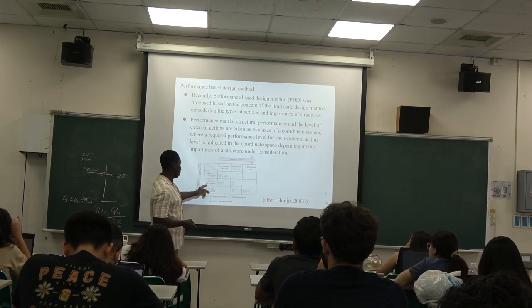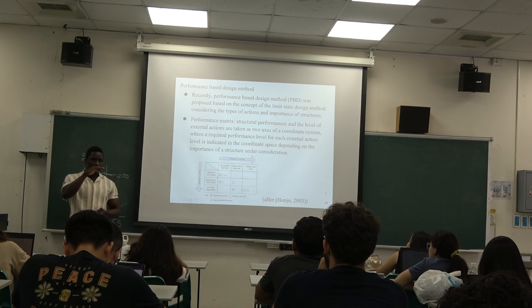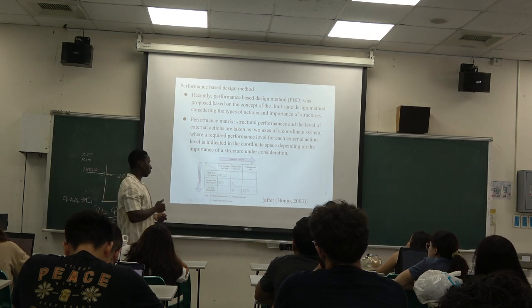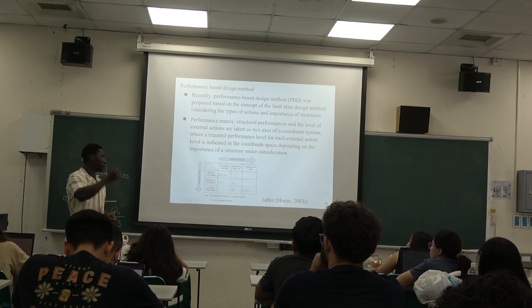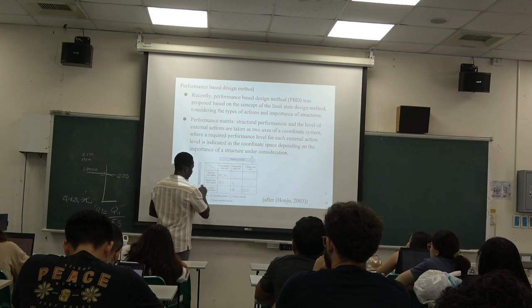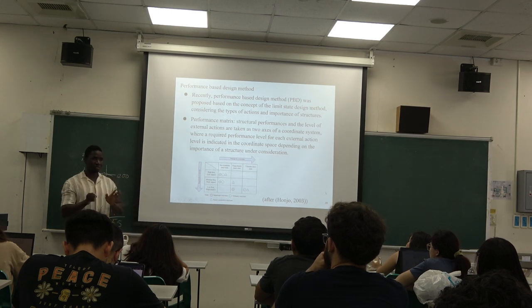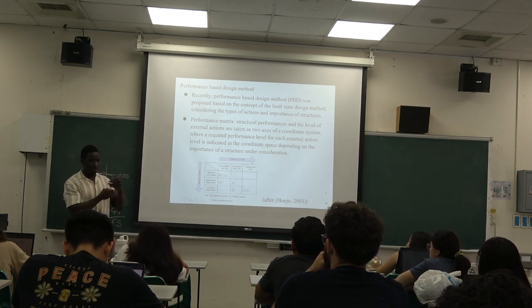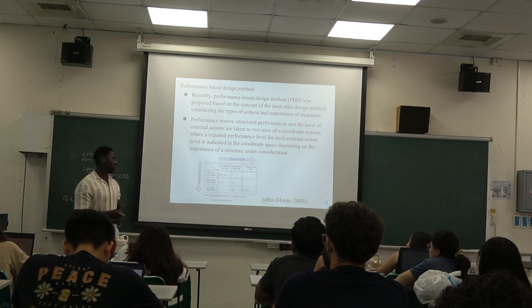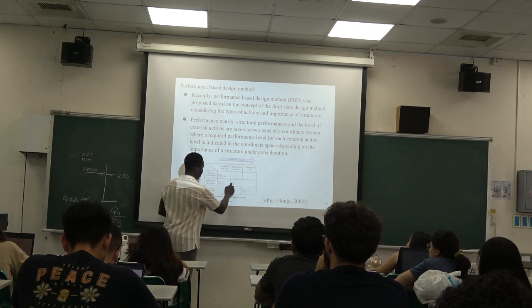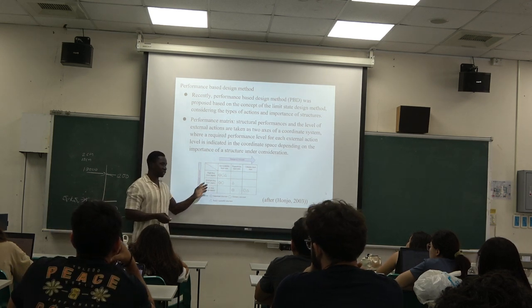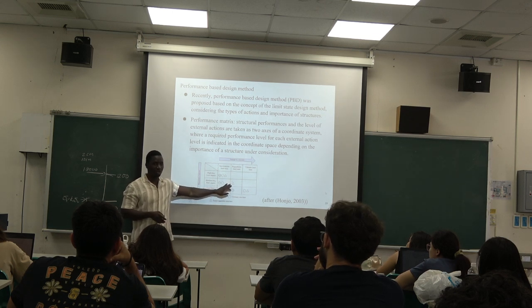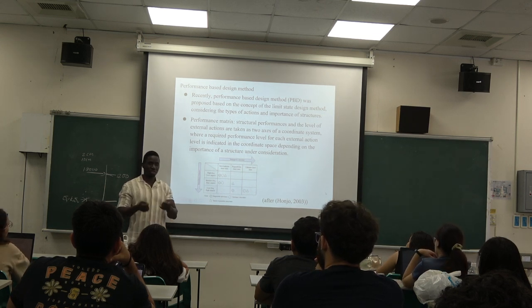You have to do some work on your structure, which is not ideal. So we come here, medium frequent, medium impact. Happens more frequently, not all too often, but the impact is not really that high on the structure. So for this, the important and the ordinary structure, we want to make sure they are still within the serviceability limit state, like nothing really happens to them. After this event, we can still use them. For the repairable limit state, it's just the easily repairable structure, and this happens medium, so we just repair because it's easier to repair this structure. You don't want to invest too much money.